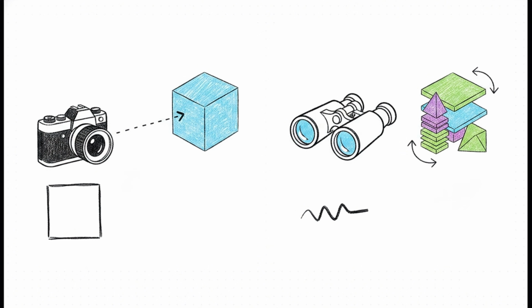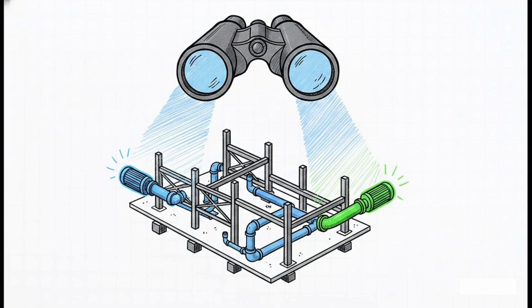But if the architect issues a new model version next week, that set isn't going to automatically grab any newly added elements. On the flip side, we have search sets, designated by that distinct little binocular icon. These are incredibly smart. They don't just remember what you clicked, they actually remember the rules you set. For ongoing clash detection, the source material lays out a golden rule. Always go with search sets if you want an updated model. As new versions of Revit files get linked in over the lifecycle of a project, a search set automatically scans the new model and pulls in any new elements that match your criteria.